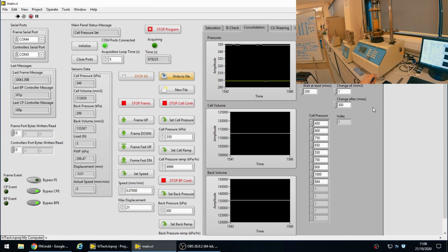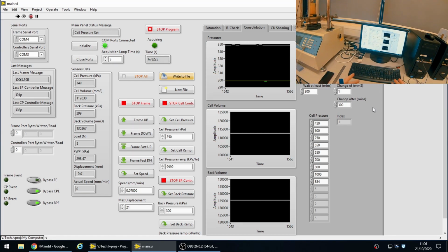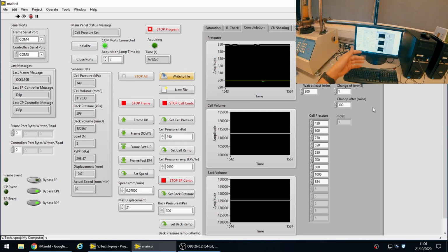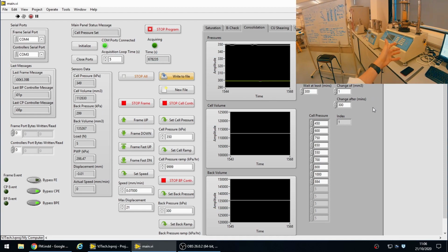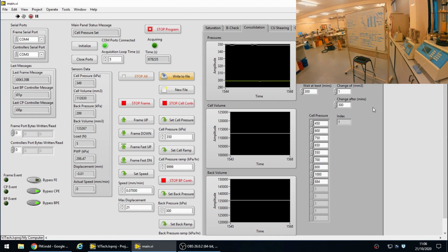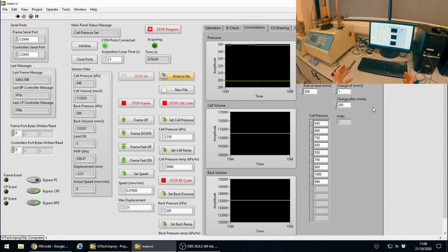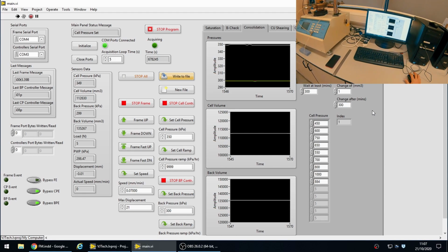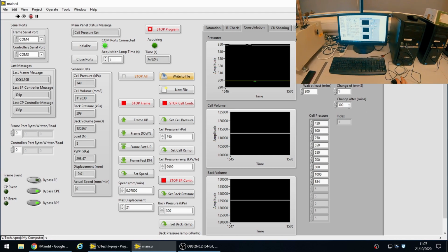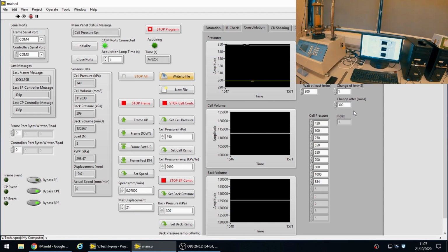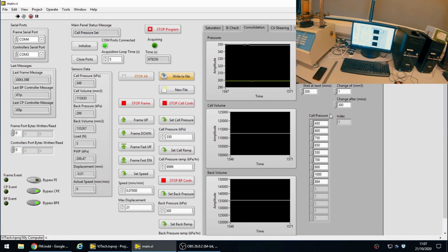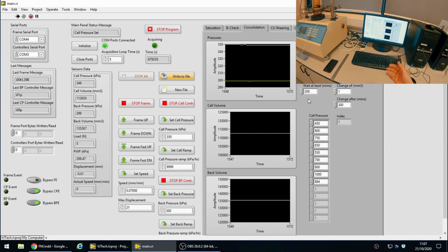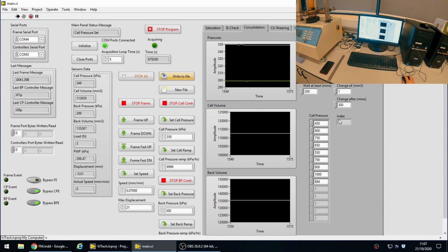If the volume changes of our sample within 300 minutes become sufficiently small, smaller than 1 millimeter cube, then you can move to the next stage of consolidation, because at that point you have finished that stage of consolidation effectively. It will take very, very long amounts of time to get to that T100, to the real T100. Or we say after 5 hours, move on anyway. So there we have it. We have 5 hours to change this sample, to increment our consolidation stress.